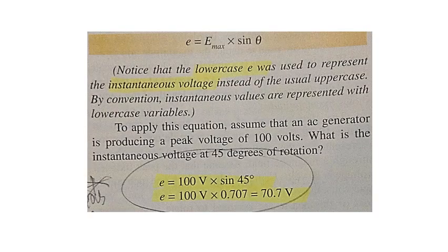Average and effective values. A study of the differences between the AC and a direct current raises a key question. What is the actual value of the AC wave? The voltage and current vary constantly to reach peak value only twice during a cycle. Often the average value of the wave is needed. The average value is the mathematical average of all of the instantaneous values during one half cycle of the alternating current. The formulas for computing the average value from the peak value max of any AC wave are shown.